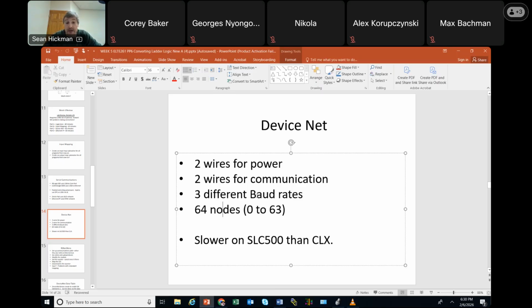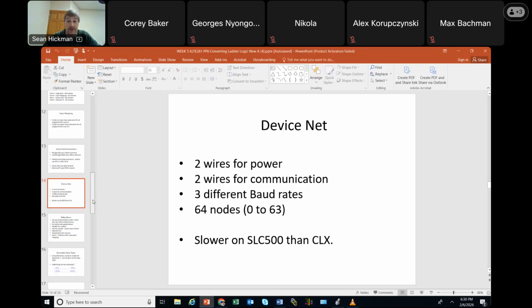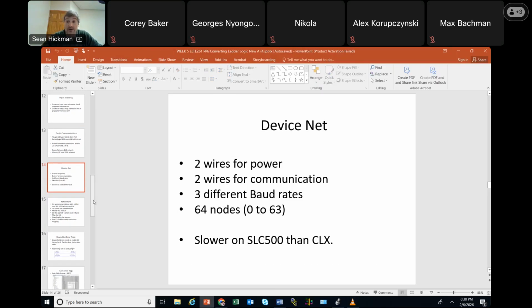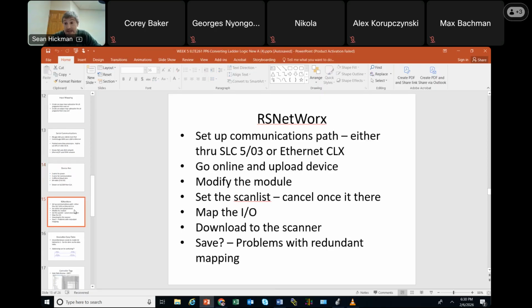Okay, so when you start getting a lot of remote IO, like robot scanners and stuff like that, you've got to be sure everything is running at the same baud rate or the same scan rate, so stuff sees each other. And if you take PLC 3, we will do a lot where you have to do time synchronization and all this kind of stuff, so everything is scanning on the same clock.